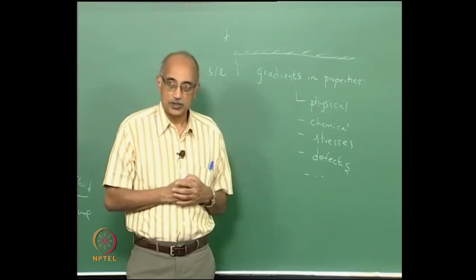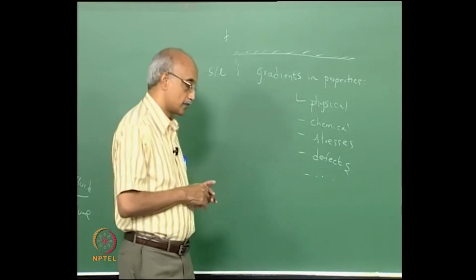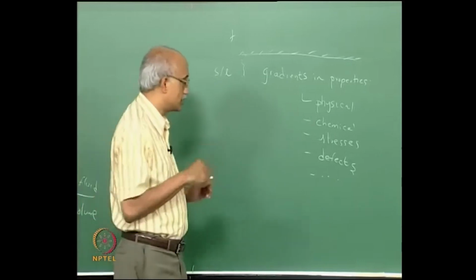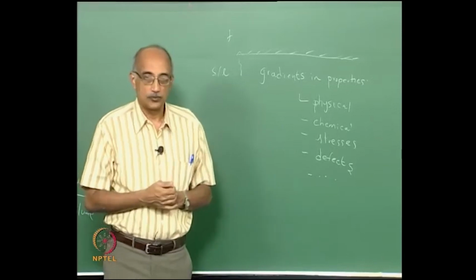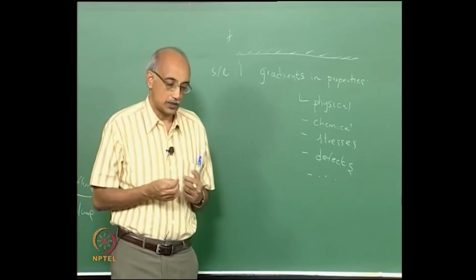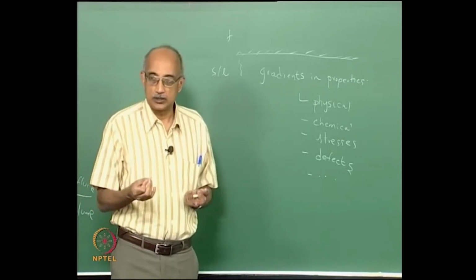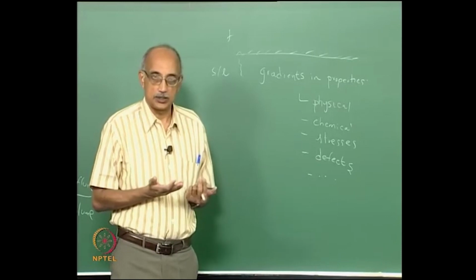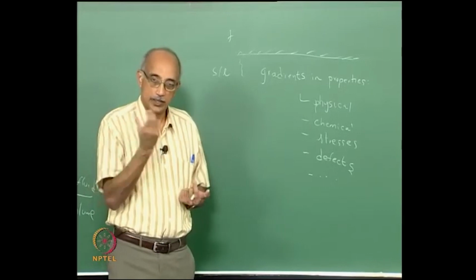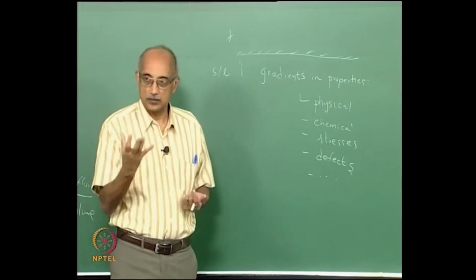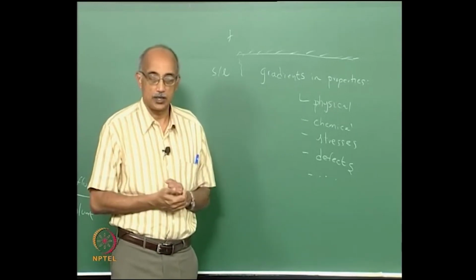Oxidation is a process that happens naturally, right? But you can also think about a manufacturing process where we are deliberately introducing a reactive gas to achieve a certain purpose. For example, when you have steels that have low carbon content and you want to increase the carbon content, there is a process called carburization that is used, which essentially takes carbon molecules and lets them diffuse into the steel surface in order to enrich the carbon in the steel alloy.